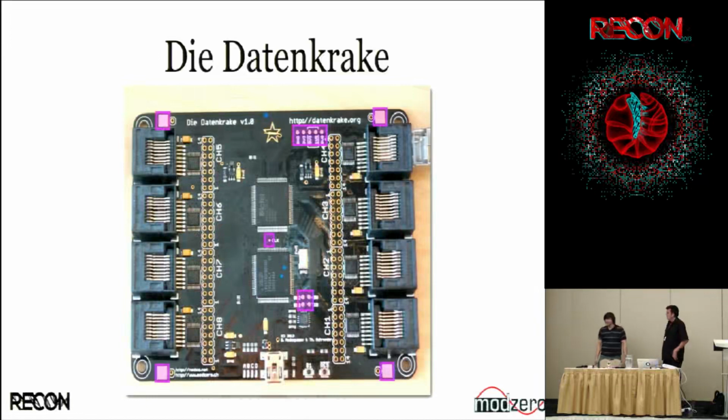Okay? But we also have these test pads, which are awesome. Don't ask me where I saw this first, but I'm giving you a free pro tip. If you design a new board, what you should do is put ground planes on the corners. Now you can take your oscilloscope probe and clip the crocodile clip right there. So it's not flying around all over the board, irritating you, getting in the way and grounding something out, and then you have chips exploding and whatnot. So, safety first.